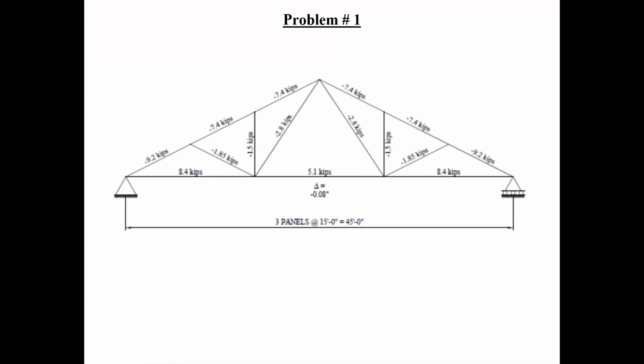And basically, if you want to know if you're on the right track when you're modeling something, first of all, if everything's supposed to be pin connected, then you only have what we call axial forces. In other words, the only force you have is the one acting longitudinally in the member. So it's either going to be a tension force, and the way the program tells you that it's a tension force is that it has a positive value.